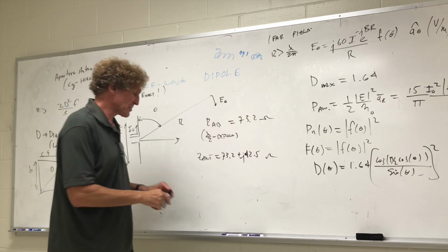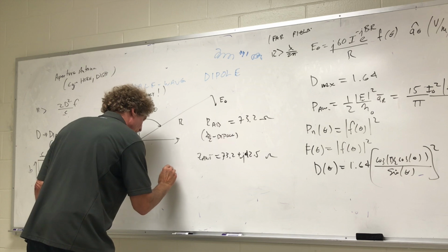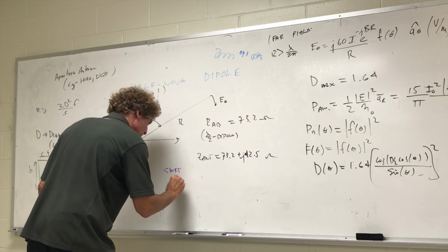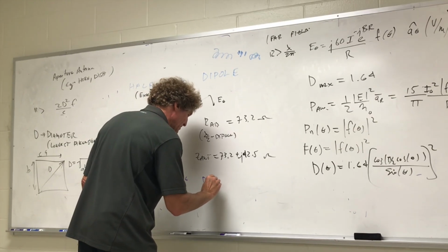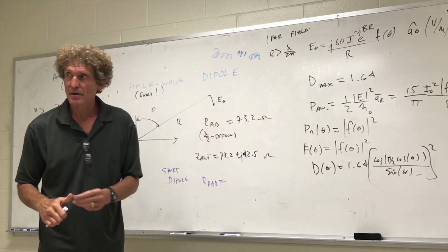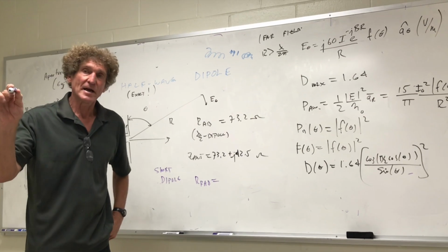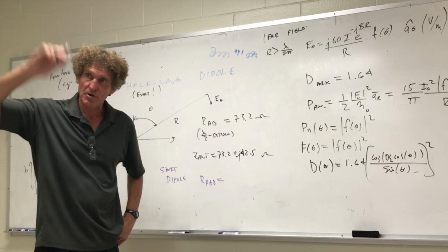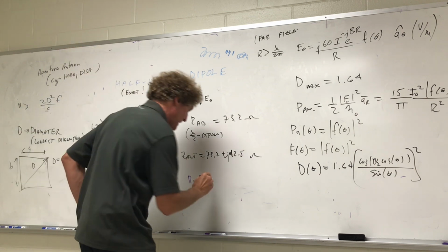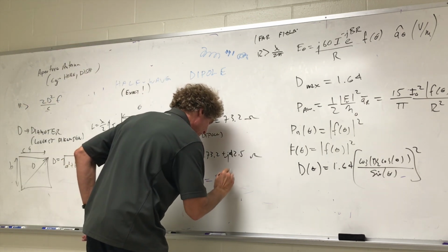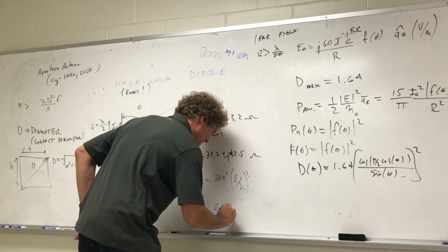That's the impedance. To contrast this with the short dipole, I'm going to put it right under there. For a short dipole, what is just the radiation resistance? This isn't even the total impedance. Do you remember? I mentioned it a second ago. Anybody? 80 pi squared, L over lambda squared. Actually, he's right. It's 80 pi squared for the one that assumes the current is constant. For the one that has a triangular current I talked about, then it would be 40, but he's right. It's 80 pi squared (L over lambda) squared, where L is the length of the antenna.